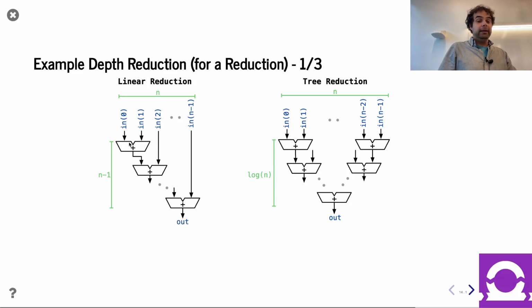And the reason why is, as you go down this linear combination, even though you may have some result, let's say it's k plus n/2 bits, whatever that is, you may not really be using all of those k plus n over 2 bits. You're only using maybe some of them. The tools don't know that, and so once again it's going to add another bit for the adder and keep growing it.